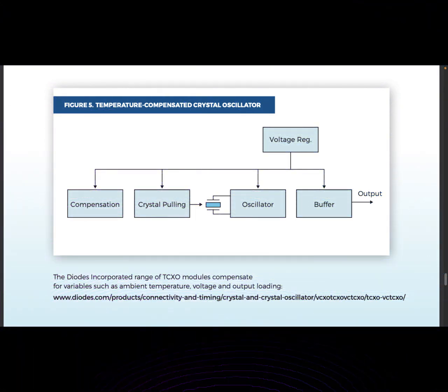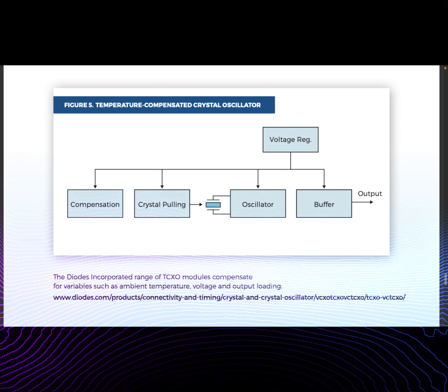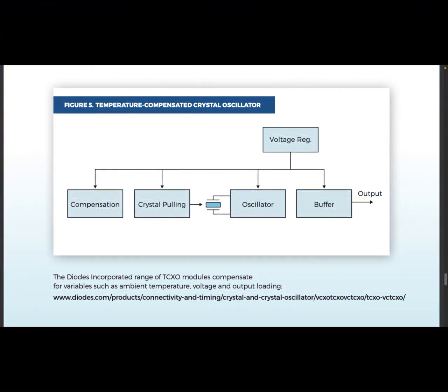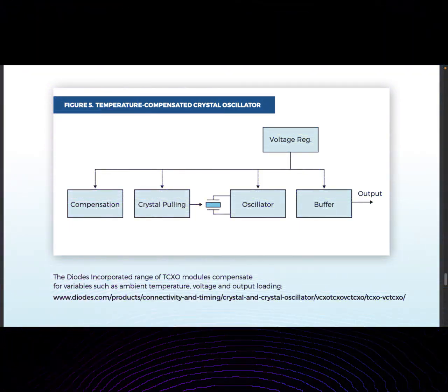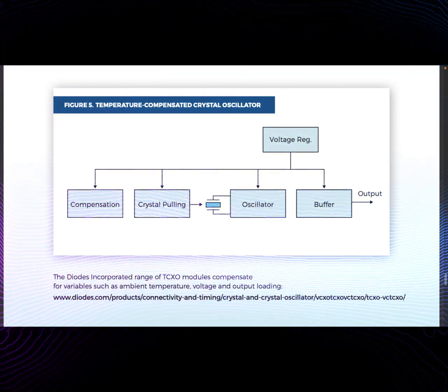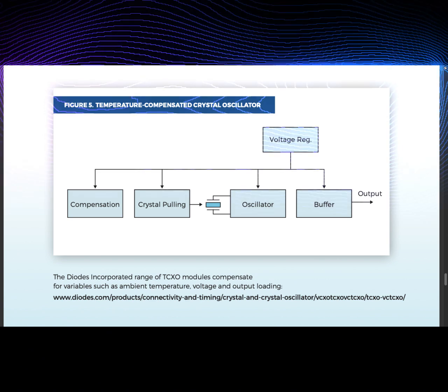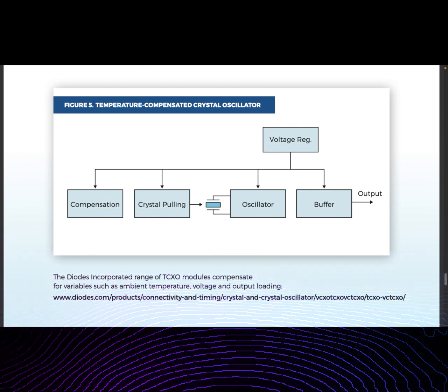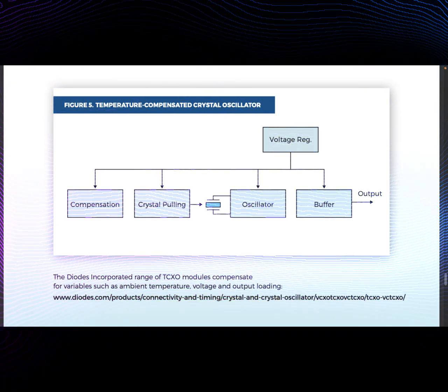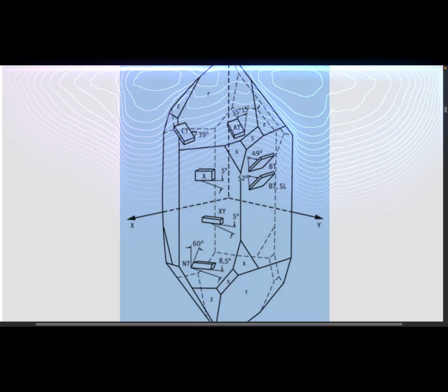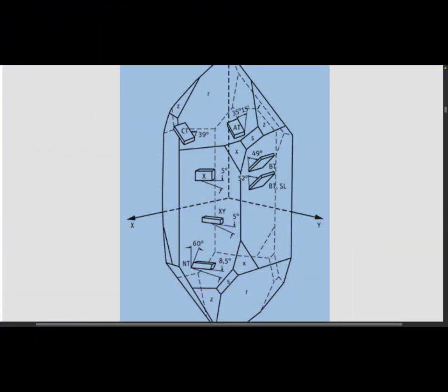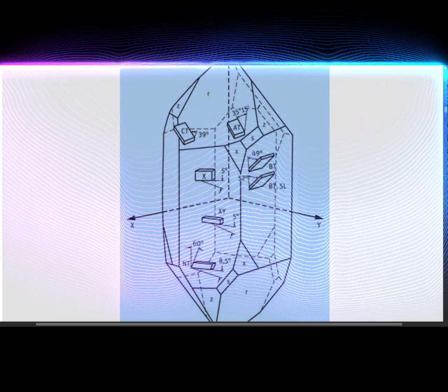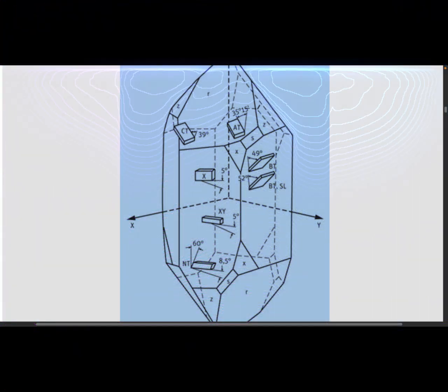A real-time clock, or RTC, typically has an input frequency of 32.768 kHz. Because of this, it can be easily divided by powers of two to generate timekeeping signals down to 1 cycle per second. This also needs to be very low power, as the RTC in the system continues to run, even in standby mode.